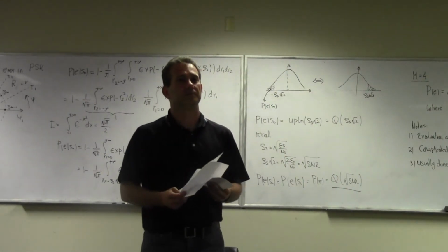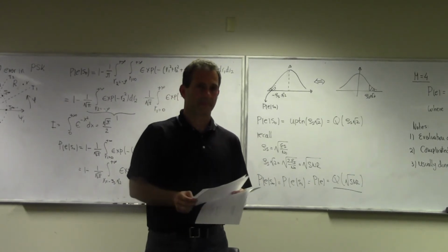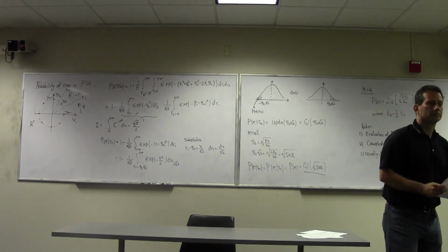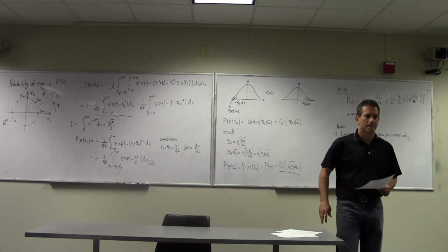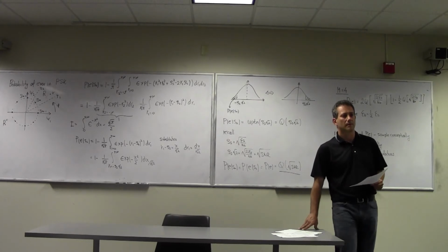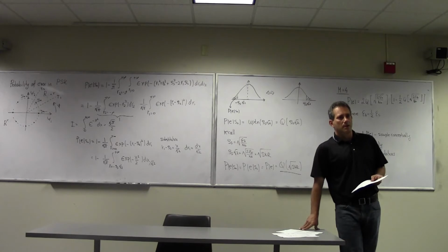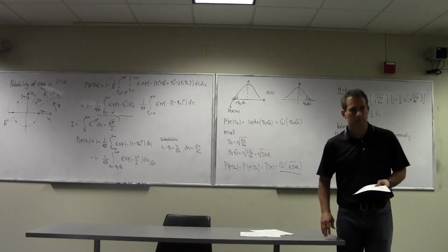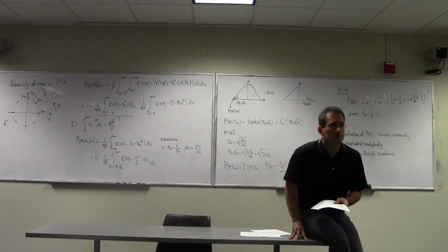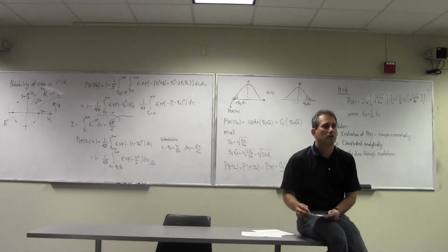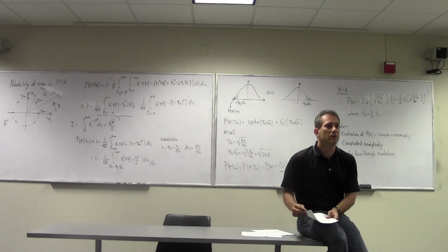So whenever somebody asks me about the probability of error in PSK, or, from the previous lecture, PAM, the only thing you remember is that for PSK you have the Q of the square root of SNR, and if you're going with PAM, it's 2(M minus 1) over M times Q of A over the square root of M over 2, and that's it. That's the end result, right? If somebody asks you that specific question, this is the specific answer you give.